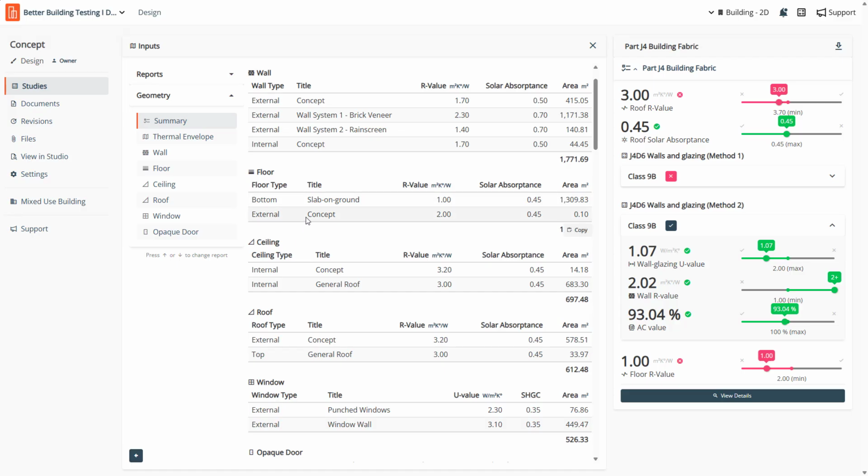And as I mentioned earlier, we've got this very small area, and it might be hard to find that one very small area where that's overlapped. So it looks like there's a geometric issue there, and it's generated. It's not going to make a difference to the results, but through some overlap, we've got a very small sliver of floor above the ground level that is popping out, and then it's deemed to be exposed to the outside. So probably a model issue.